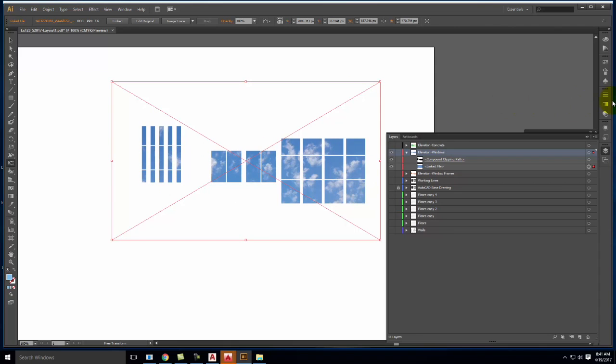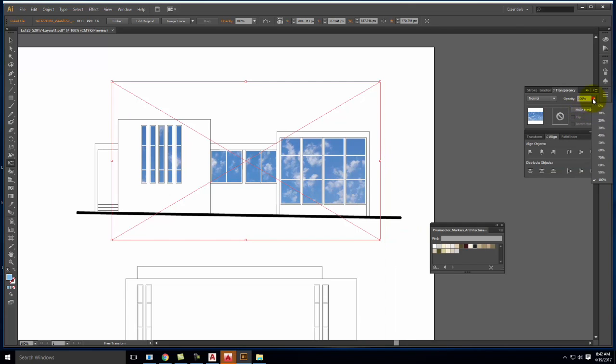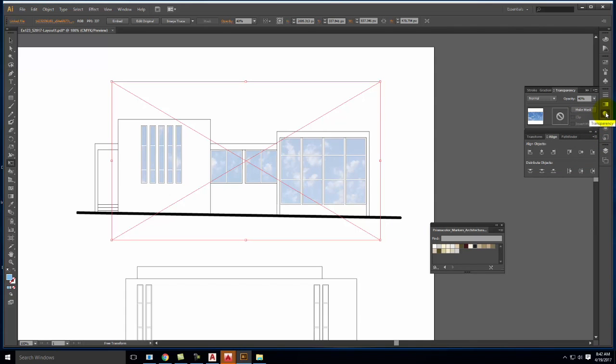It's probably a little bit strong if I were to turn back on... well, number one, I have to move this below the lines. But if I were to turn back on my lines, those are probably a little bit strong still. So I would take my windows, go to my opacity here, and probably drop my opacity down to maybe 40%. Well, you can't see it. For my actual version, I would probably do 40%. For you guys, so you can see it, I might go to 70%.